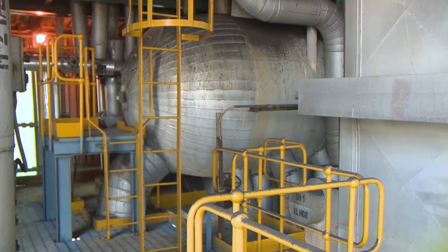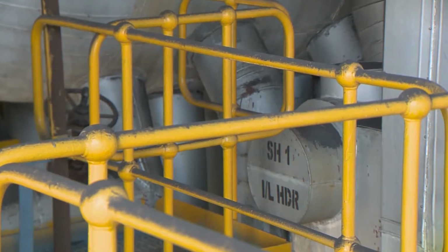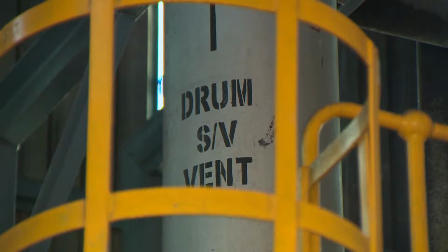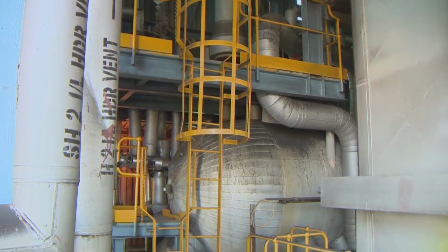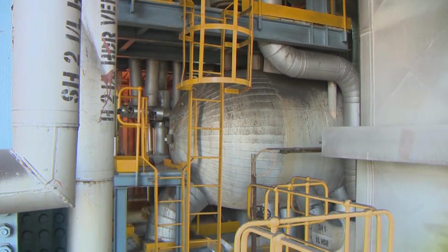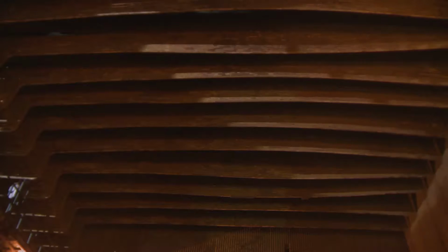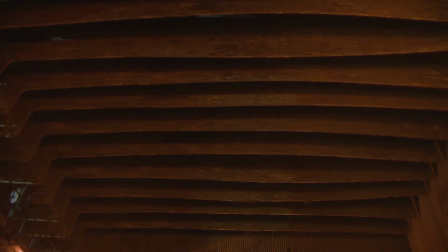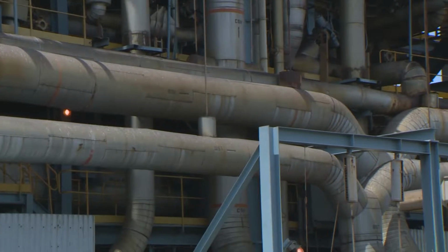Steam and water is separated in drum, where the water goes down to downcomer again, and saturated steam goes to superheaters. Required safety valves have been provided in boilers to safeguard the vessel during abnormal pressure rise. The saturated steam passes through 3 stages of superheaters and picks up more heat from flue gas to become superheated steam. The superheated steam is carried by main steam line to the turbine.